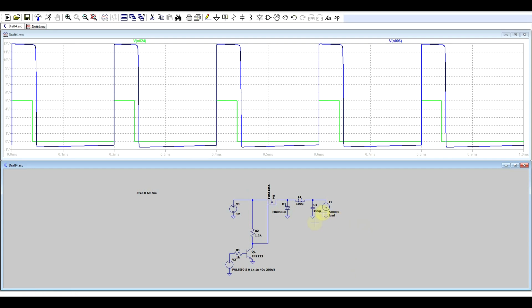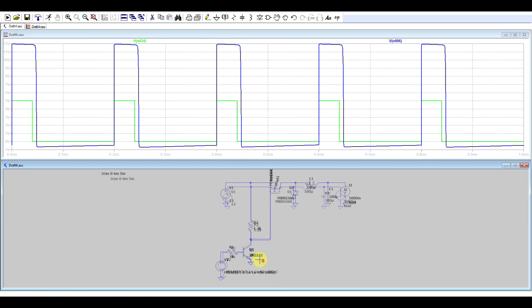So the problem we're getting here is that even though the voltage in the switching node turns high almost exactly as the input signal does, we can't say the same thing about the signals going low. The difference is that to pull the signal high, you need to turn on the transistor, and you're doing this using the low side transistor in the circuit, whereas to turn it off, you're relying on this resistor.